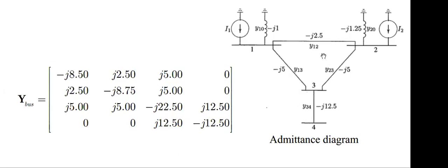Then from the per unit diagram, you can have the information to generate the impedance diagram by yourself. First step, the impedance diagram drawing. When you complete the impedance diagram, then you can modify it for the reactance diagram.